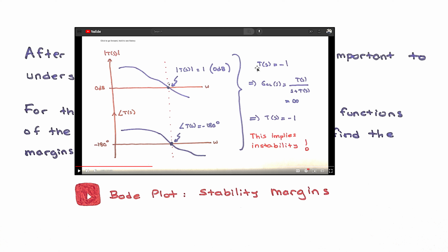So the L will be related to T of that video that I explained Bode plots and how we find stability margins. Basically, L of S that we are going to find will pop up in the denominator, 1 plus L of S. We call it return difference transfer function. And by looking at L, like in here, we can assess margins of the closed loop system.